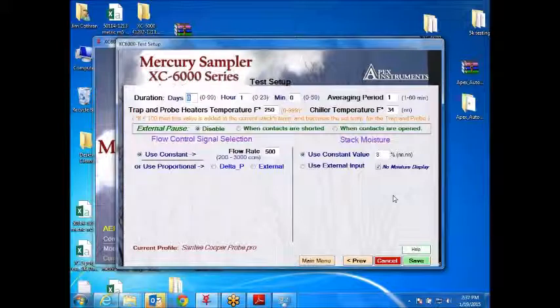If you've got questions, the biggest thing I imagine, in the past, I don't know if you've been running just constant runs all the time. Well, we were trying to get a baseline before, and we would check it randomly. And we kind of played around with flow rate and temperatures until we got it to where we could get about a 5-day run without having a wet trap. Understand? Yep. So that's how we did it.